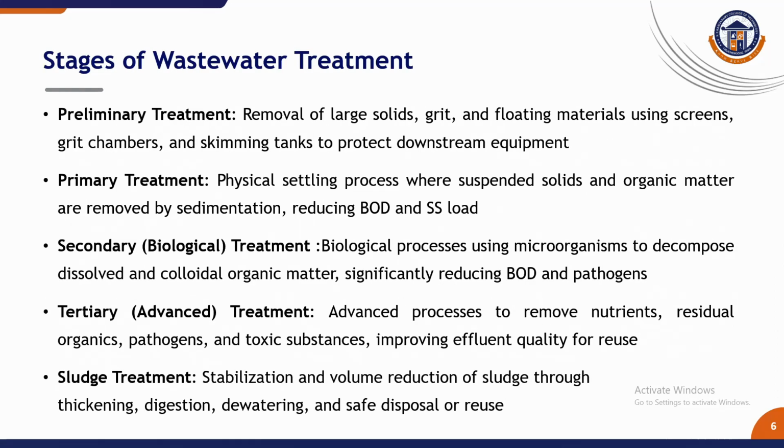Wastewater treatment is carried out in several stages. It starts with preliminary treatment, which removes larger solids and grit. This is followed by primary treatment, where suspended solids are removed by sedimentation. Next is secondary or biological treatment, where microorganisms degrade organic matter. Then comes tertiary or advanced treatment, which removes nutrients, pathogens, and residual pollutants to improve effluent quality. Finally, sludge treatment is carried out to stabilize and safely dispose or reuse the sludge generated during treatment.